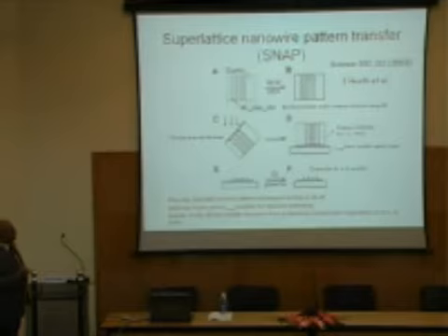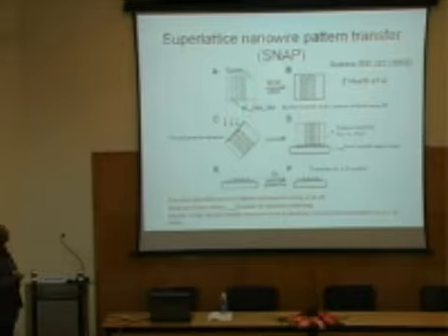And in this example, what is shown is you have a gallium arsenide substrate, and on that gallium arsenide substrate you have some aluminum gallium arsenide semiconductor, and then you etch it in such a way that part of it goes away, so the top part is exposed, and then you can remove that gallium arsenide by some chemical methods, and after that